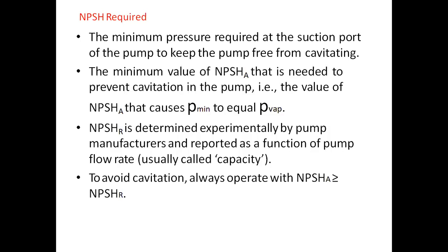NPSH required means the minimum pressure required at the suction port of the pump to keep the pump free from cavitation. For that, we have used NPSH.